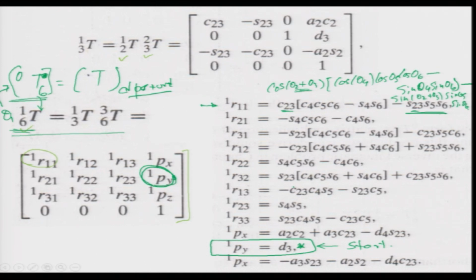So, if I want to remove theta 1 from here, I take the first matrix, T 0 to 1, take its inverse and bring it onto that side. Now, if I bring it onto that side, what it essentially means is that I have 1 to 6 on this side now. 1 to 6 would mean that the variables are now theta 2 to theta 6. Theta 1 has gone to this side now. So, that is the basic philosophy, or the process, for trying to solve for the PUMA.